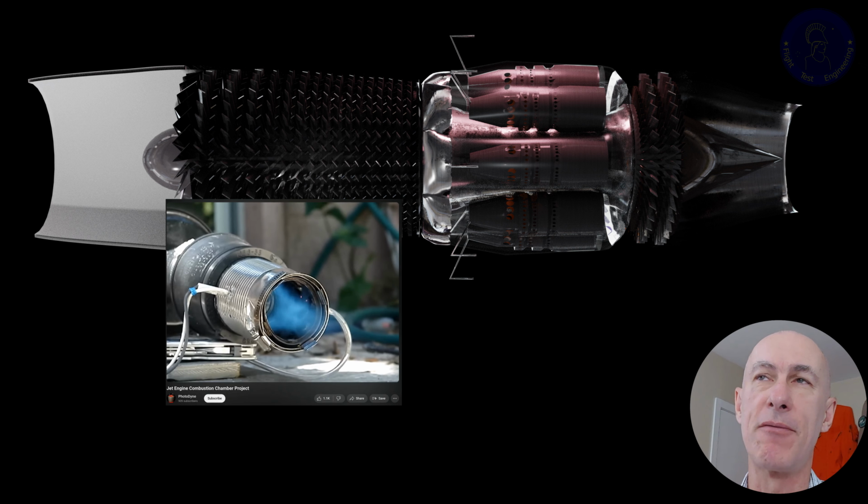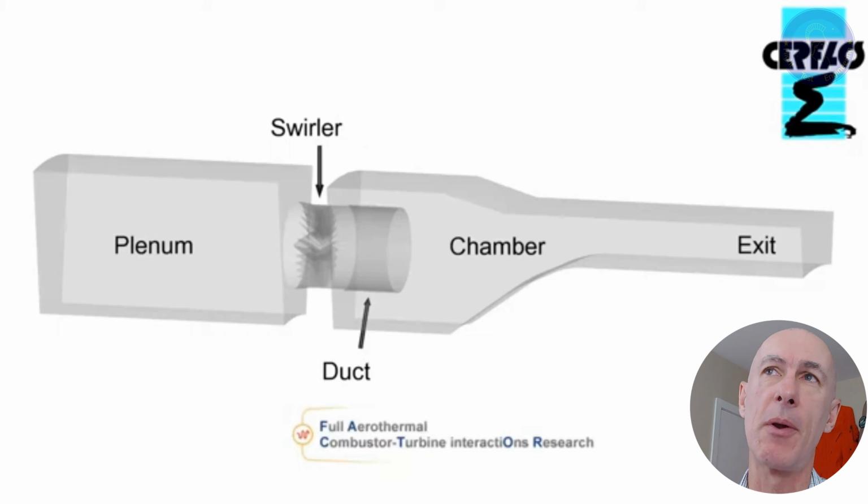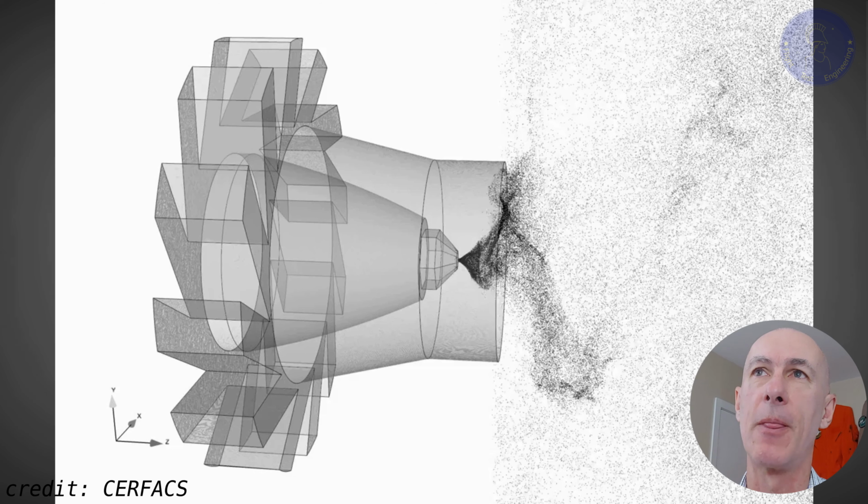In order to keep the flame alive, the main mechanism is to have recirculation and turbulence. Because when we have the hot gas being sent back, it will mix with the unburnt fuel and ignite it. So the idea is to have this recirculation. Typically, this is implemented with a swirler, which induces a vortex into the incoming airflow.